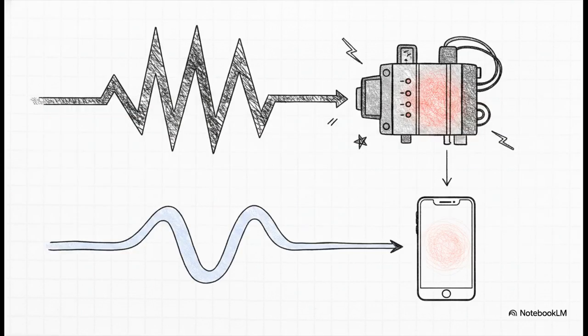So, the absolutely crucial point for the uplink is that SC-FDMA limits power spikes, which is exactly why your phone doesn't just die in 10 minutes when you upload a 4K video. If we used OFDMA for uploading, the signal's power would wildly fluctuate, and that would require your phone to have a massive, expensive, and power-hungry amplifier just to handle the peaks. SC-FDMA smooths out those peaks entirely, keeping the electronics in your pocket cheap and efficient.